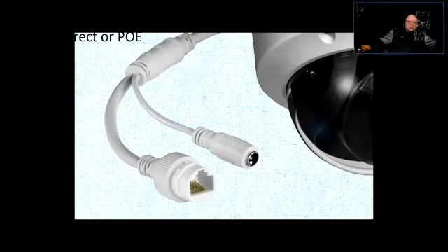Now, I kind of discourage that kind of thing, because when you're powering the cameras from different locations in the facility, and the facility is big enough, you could end up with a problem called ground loops, because the grounding or the neutral cables could have slightly different levels on different panels. In the audio system that manifests as buzzing, and in the video system it manifests as some interference on the video signal. There could be some stripes running through or something like that.